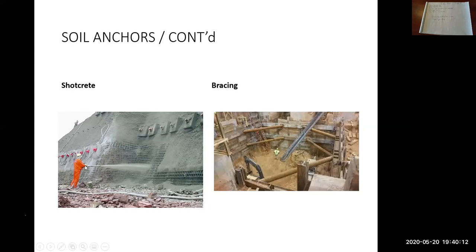You can see he or she is decked out in all of this gear. Every piece of skin is covered with protective equipment, gloves, face mask, etc. You can see the mesh there underneath. Here's shotcrete that's already been sprayed. This person is filling in this section here. These are previously installed anchors there and then along here.